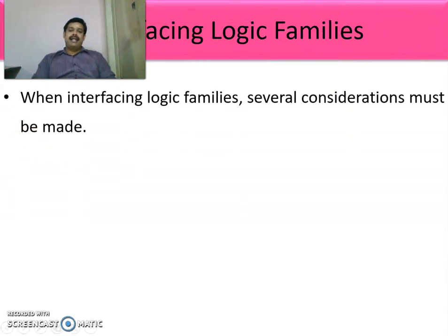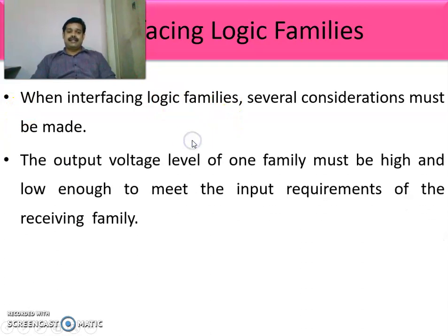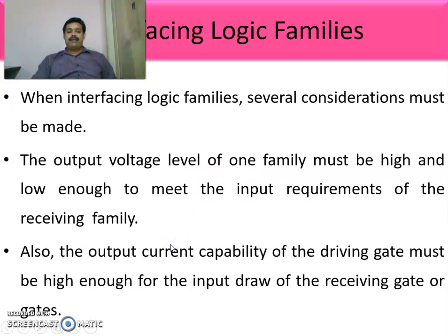So in interfacing logic families, we have to consider many things. The output voltage level of one family must be high and low enough to meet the input requirement of the receiving family.